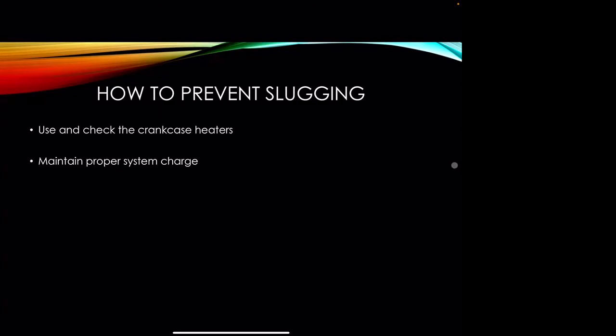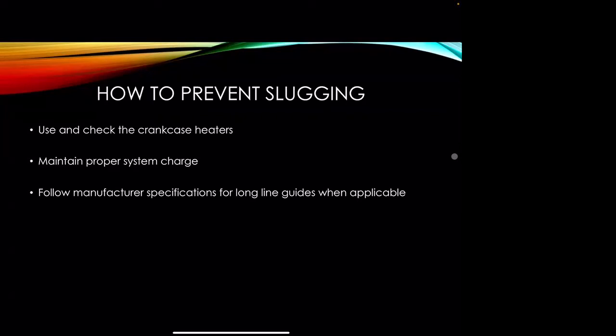Maintain proper system charge. Don't overcharge the system. Don't let it constantly be undercharged and you're adding refrigerant to it every 6 months. Maintain proper system charge. And then if we have long refrigerant lines, again, follow manufacturer specifications, especially when applicable.